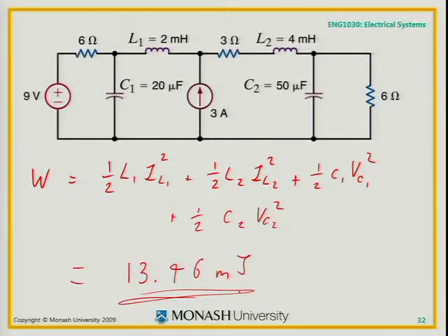So the idea there, at DC steady state, direct current, meaning that all of the sources are just direct current things, 6 milliamps current sources or 12 volt voltage sources. At DC steady state, circuits with capacitors and inductors don't really hold anything new for you. Inductors short circuit, capacitors open circuit, you just analyse normally. You might be interested in finding currents through inductors, voltages on capacitor plates, because it tells you about the energy stored.